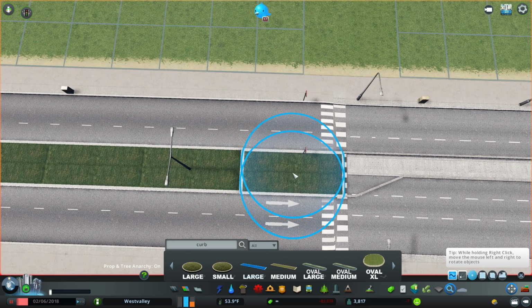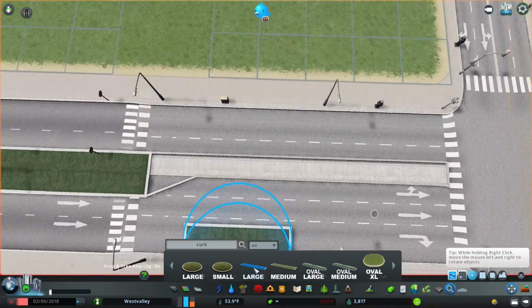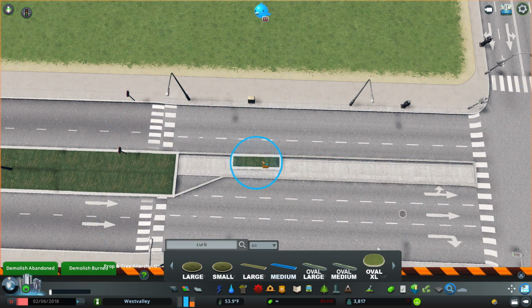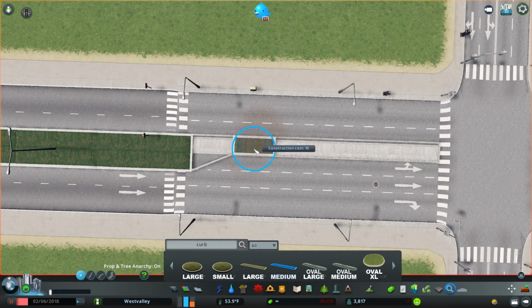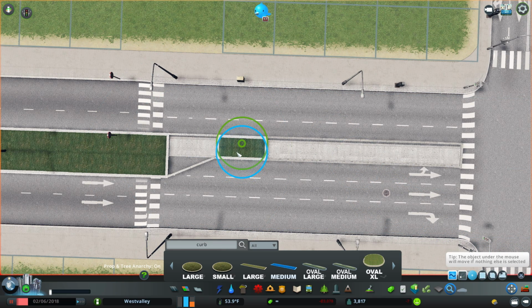And then right when I get near the intersection, I'm going to just copy it up to a certain point. I'm just going to select the last two ones here. Copy it up to there. I'm going to start drawing where the left turn pocket starts. I'm going to just draw this section like that. So then once you make your template, you can just copy this up until the end of the curb.